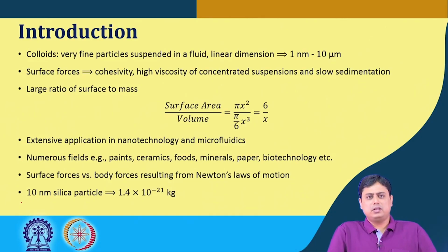It can exhibit the behavior of high viscosity of concentrated suspension, and it also results in very slow sedimentation. That is why we spoke about sedimentation in some external field like the centrifugal field, because by gravity separation this kind of fine particles cannot be separated. These remain suspended for a longer time.